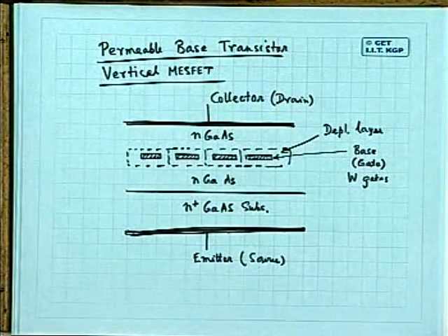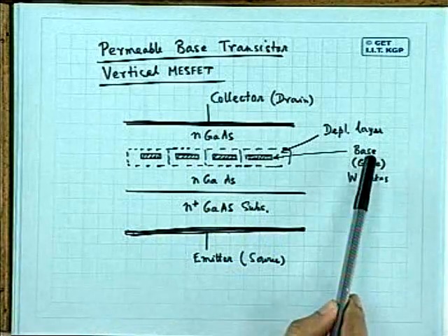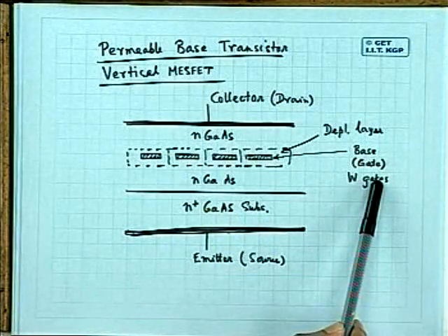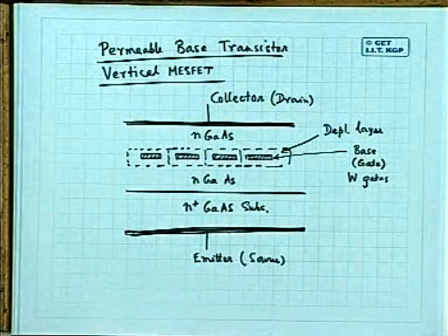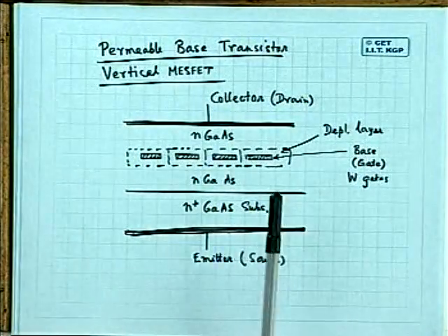And you can design it in such a way that it will behave as either an enhancement mode device or depletion mode device, depending on the spacing of the grids. It is very similar to triode, pentode. Have you studied a little bit of vacuum electronics, triode, pentode, grid structure? Very similar to that. So you interplace a grid of tungsten electrodes, which are separated, but spacing is adjustable in your design.